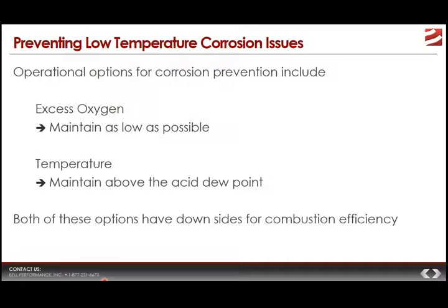So you can't drop it too low, or else you're going to start sacrificing combustion efficiency, and you definitely don't want that. The second thing that they can do is try and raise the exhaust gas temperature so that it gets further down the cold end before it cools down enough to drop below the dew point. Now, how do they do that? How do they affect this temperature? Well, they do it basically by increasing the gas volume, which is the exact opposite of this.